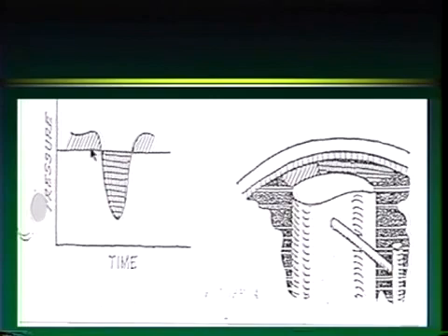And so what happens is we actually get a negative pressure at this part of the foil. And what will that do? That will actually bring material from the accepts back to the feed side momentarily. Okay? So we get this spike in negative pressure, and that is actually a back-flushing action. And that back-flushing action is going to be the mechanism where we keep the face of our screen plate clean.